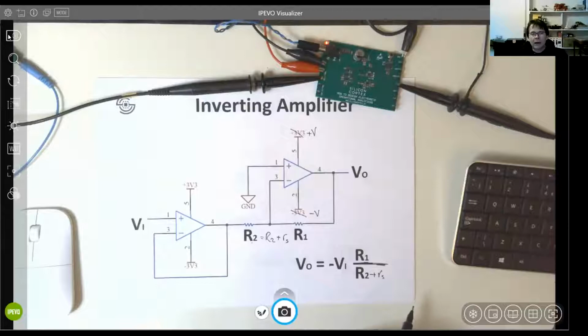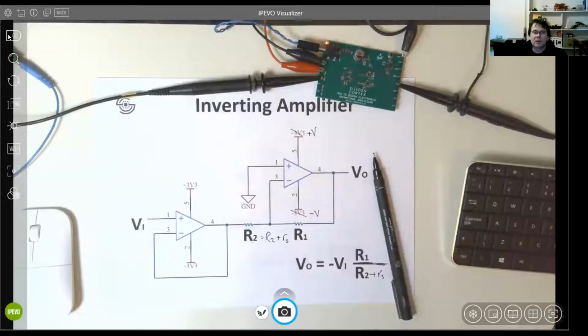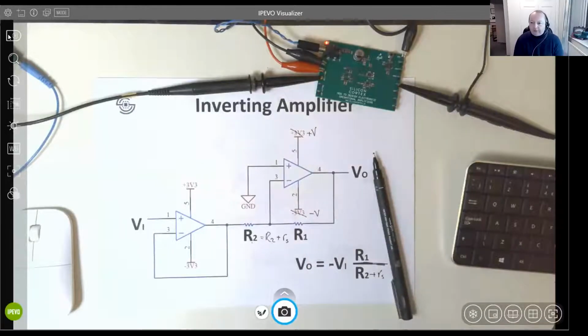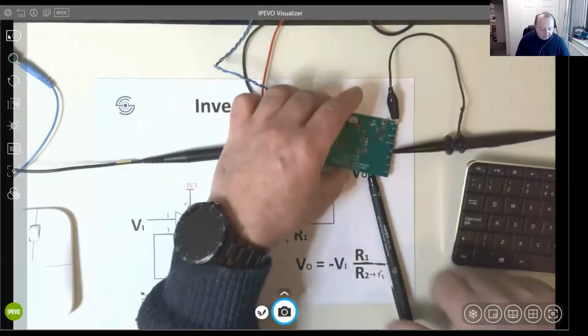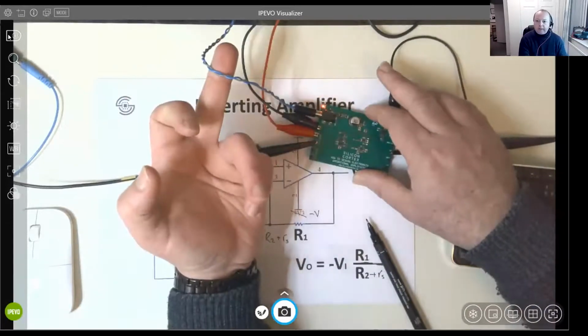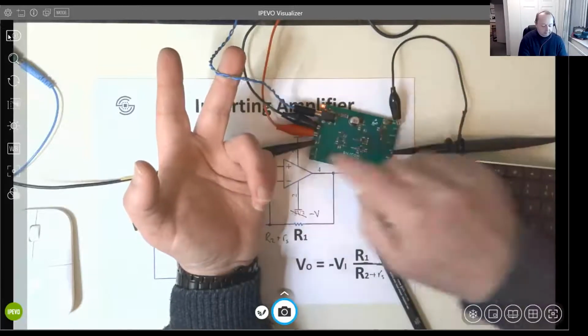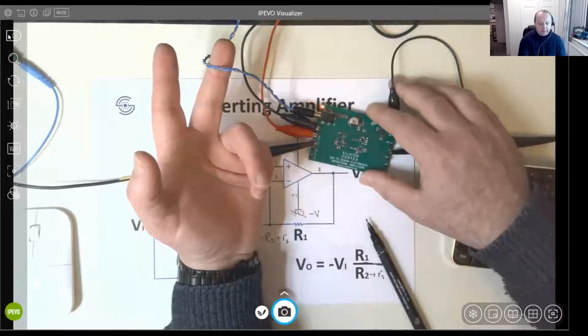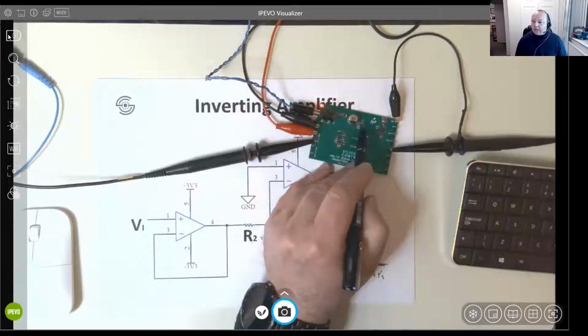Yeah, the question was really about how I'm thinking in terms of a circuit where I've got a battery as my power source, so I've got a negative end and a positive end. Oh, I see. Here you've got 3 voltage levels, presuming your signal ground is halfway between your V plus and V minus. Right. So to answer that question, if we go back to the very first session on power supplies, I had a section in there on how to create a negative voltage from a positive voltage. You go through a small chip. So on our board here, I've only got a 2-wire input, just as you say, with plus 3.3 and 0 volts. How do I get minus voltage? I've got a small voltage inverter circuit on here that creates it for me.